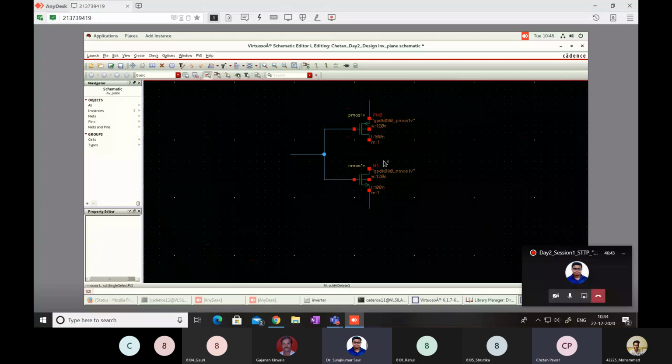Okay. So if you want to make this connection between these two nodes, you just need to type W. Then the wire node will get connected to the cursor. You just need to one time click on node, move the mouse, and then again one time click. So like this way you can click the terminals. So are you following? Yes, sir.